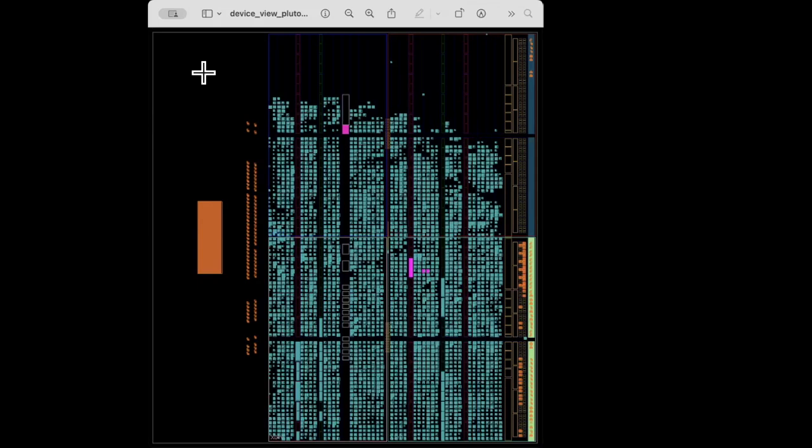When you interleave, the position of all those bits is all over the place. So what looks like a crash of static or a loss of signal, a dropout in time, when you get it into the receiver, you've rearranged all those bits, and those errors are now spread out all over the entire thing, and that is easier to correct. So those are two different ways.